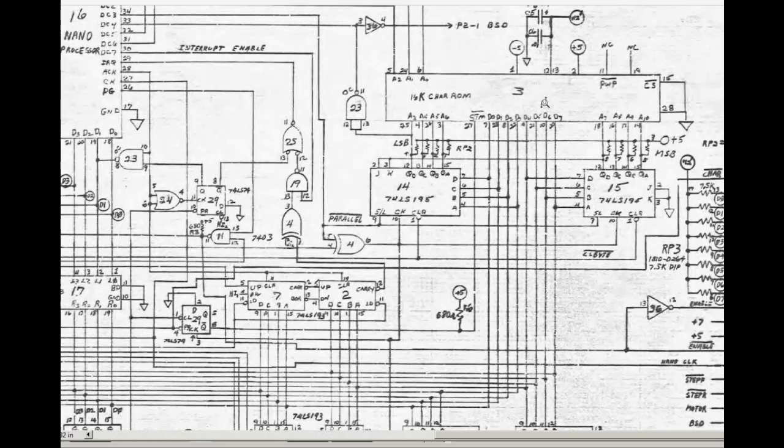So as with a CRT character ROM, each character is made up of a number of separate bytes that create a bitmap image of that character, and they are used in turn as each line of the display is scanned.